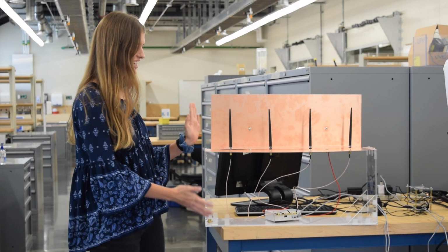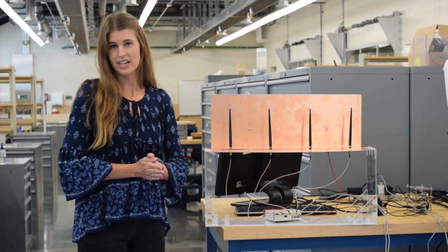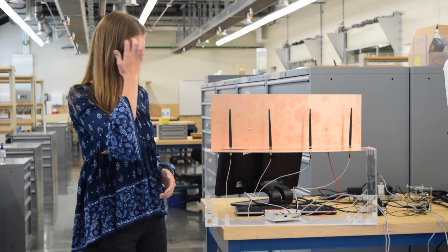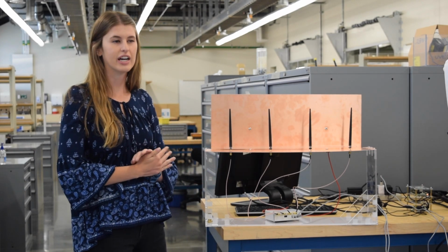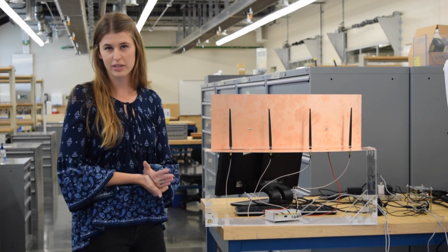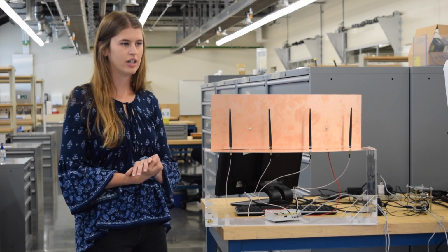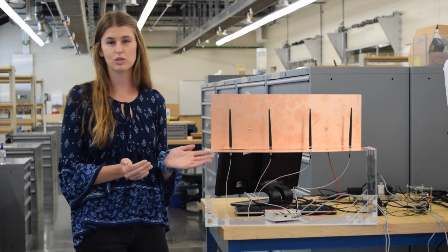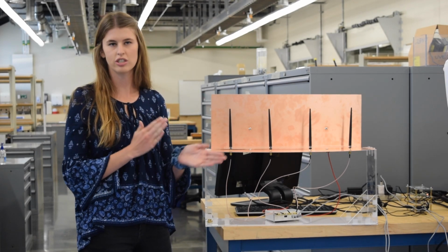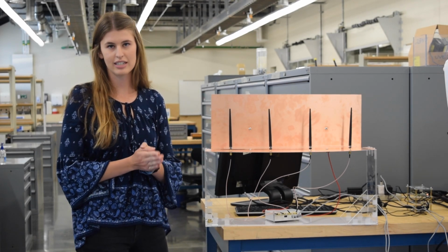That is then used to draw the waves that you see on the projector. So in designing the antenna array, there were a couple of design decisions that we made. We had to decide how far apart the antennas were going to be spaced. We decided on half a wavelength. We also tried out a third of a wavelength, but we noticed that the performance is better with half a wavelength, which is traditional for DOA to use that spacing.